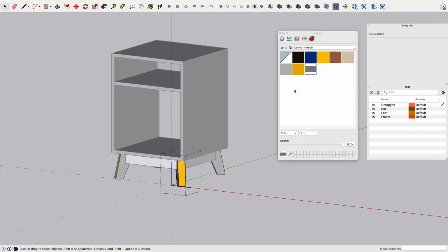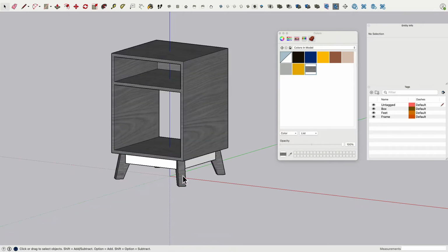Very good. So you see already here what the difference is when I add the material to the face, or if I add the material to the object. Oh, interesting. You see, it doesn't even work. So that is why number one rule, never drag a material onto an object or component. We only do this to the face when we edit the group or the component.